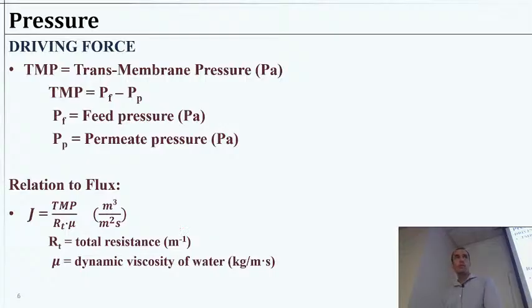per meter. So it's kind of like how much resistance is there in a meter of this membrane. We never have a meter of it in terms of distance water traveling through it, but it's convenient to stick with meter units. That means we can use pascals for our pressure. That relates us to meters and kilograms and all that. And that means our dynamic viscosity, which we relate in kilograms and meters and seconds. All of that fits together nicely so that our flux, according to this equation, will be in cubic meters per square meter per second.